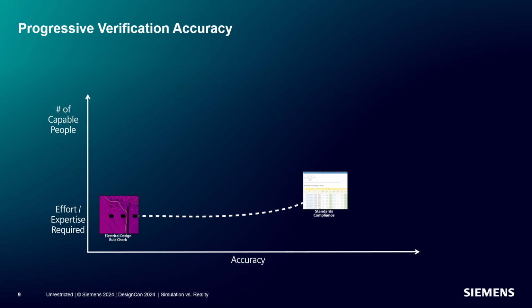This should help to weed out a lot more of the issues with somewhat minimal total time. We can perform this test as a 2D simulation or a 3D simulation. This again starts to get into the granularity of the results versus time invested. A 2D simulation is much quicker to set up and perform, and anything failing on a 2D test will certainly fail on a 3D test. But a 3D test requires more time and is more accurate.